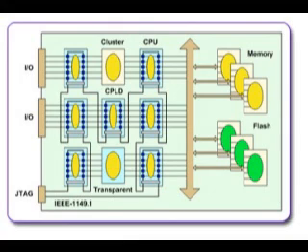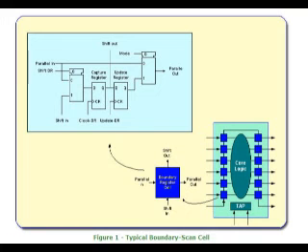The boundary scan test architecture provides a means to test interconnects between integrated circuits on a board without using physical test probes. It adds a boundary scan cell that includes a multiplexer and latches to each pin on the device. Boundary scan cells in a device can capture data from pin or logic signals, or force data onto pins. Captured data is serially shifted out and externally compared to the expected results. Forced test data is serially shifted into the boundary scan cells. All of this is controlled from a serial data path called the scan path or scan chain.